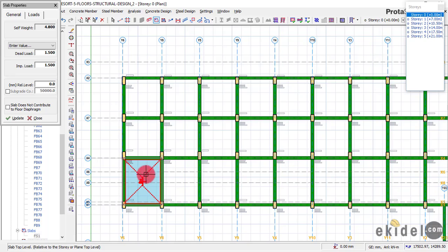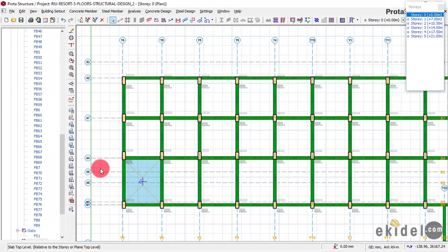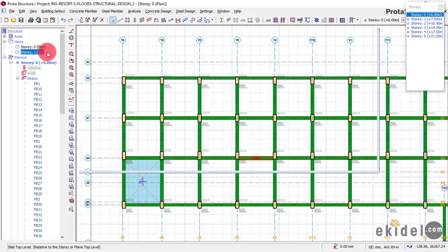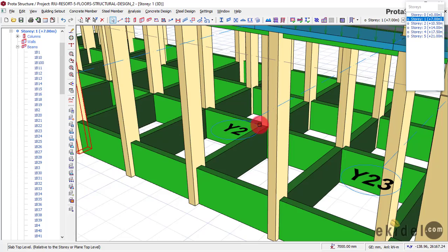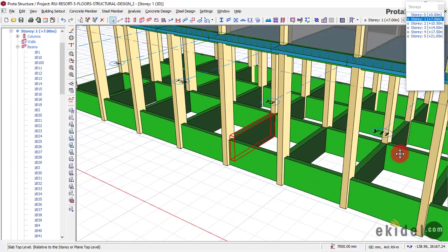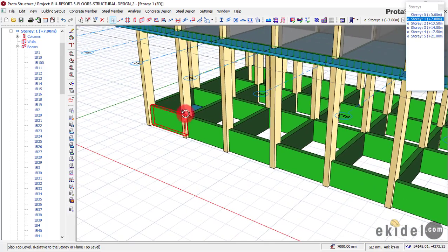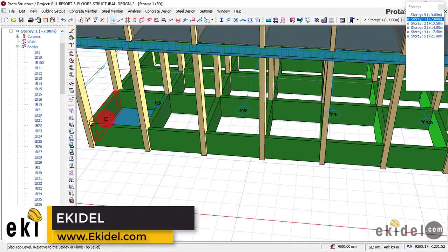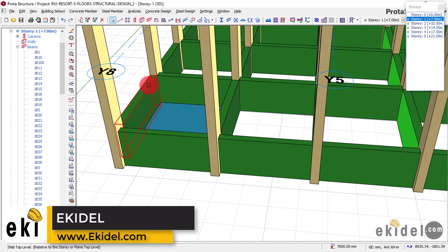Okay, so right now, let me show you what happens when you don't put this level, which is called relative level, on your slab when you're designing for a raft foundation. I'll just go here and say escape, and then I'll show you the 3D view of what this slab looks like without relative level. If I go here and look at my slab where I put my raft slab, you can see that this raft slab here is below and not above here.